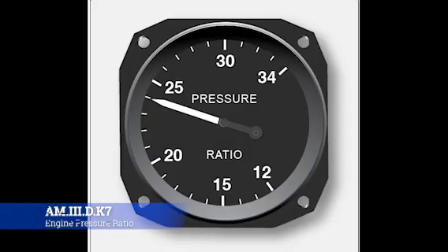Okay, EPR is another one, the engine pressure ratio. EPR is another engine indicating metric that is specifically for the turbine world. It's the key parameter in all jet engines, be it a turboshaft, a turbofan, whatever. It's the indicating ratio of the turbine discharge pressure to the compressor inlet pressure. So it's saying this is the air coming into the engine, and this is the air that's going out of the engine, and how do those two pressures compare to one another.